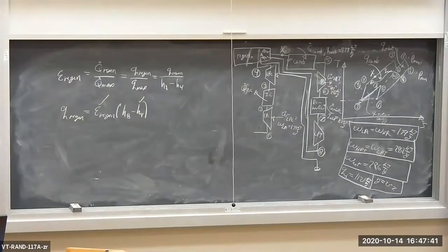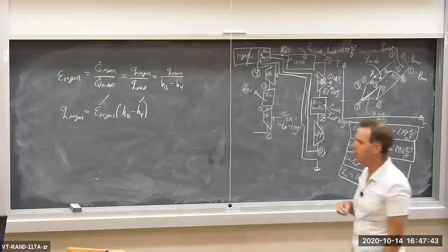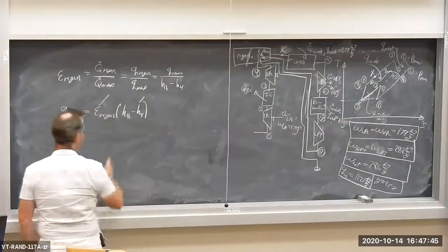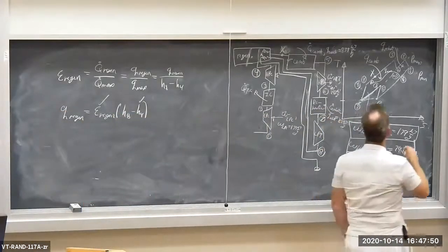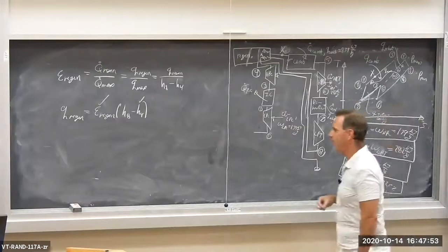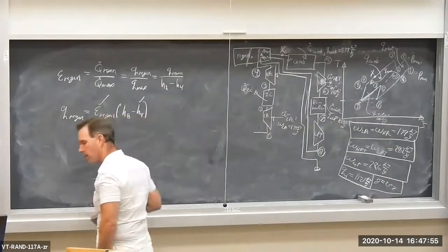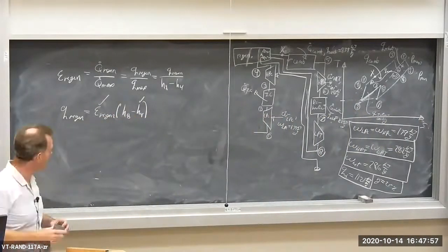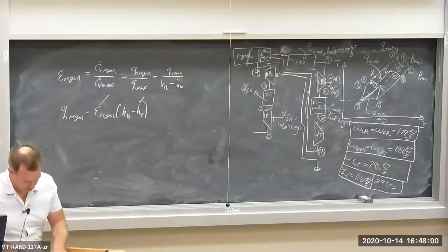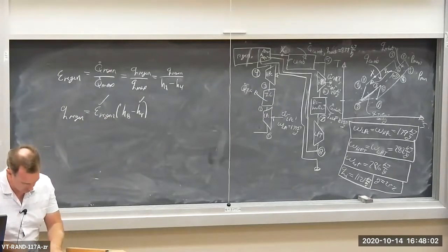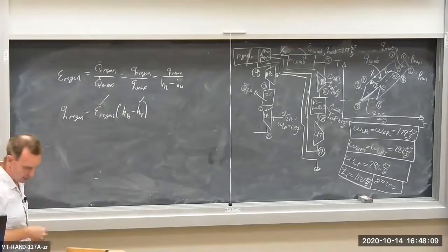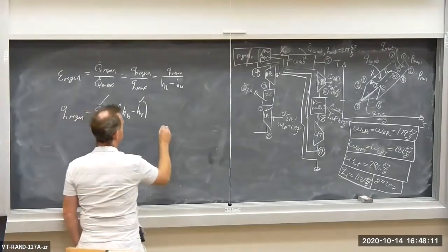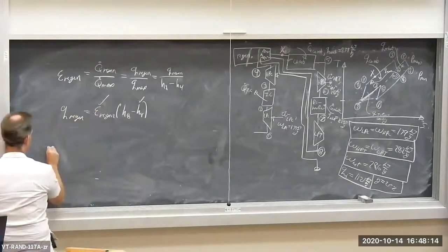I must have had it because I calculated the combustor inlet, so I can go find this again. H8, that is the low pressure turbine exit enthalpy. Okay, we need to calculate some of these things. Let me see if I can find H4 here. H4, I have it here somewhere. Yeah, 439. So H4 is 439.